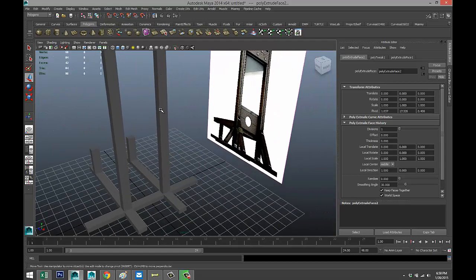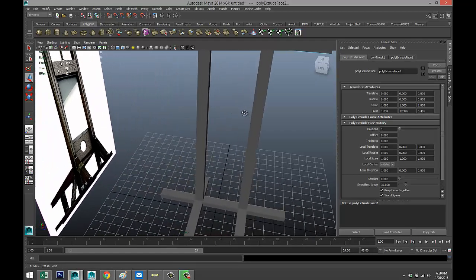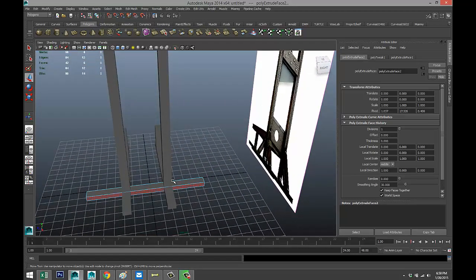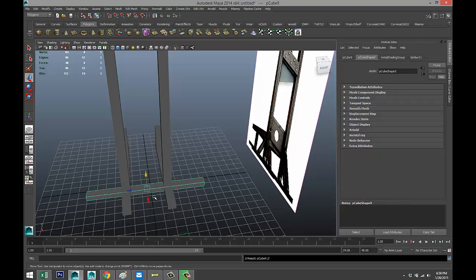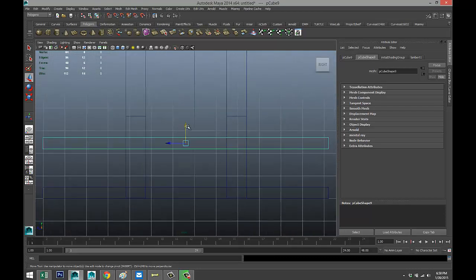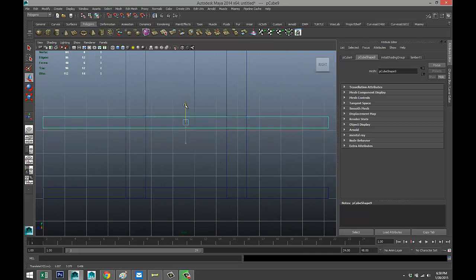Okay. Now we are going to create a cross section that has to go up. So take that guy, right click object mode, Control D, raise that up. And we want that to be level with the guys in the back. There we go.